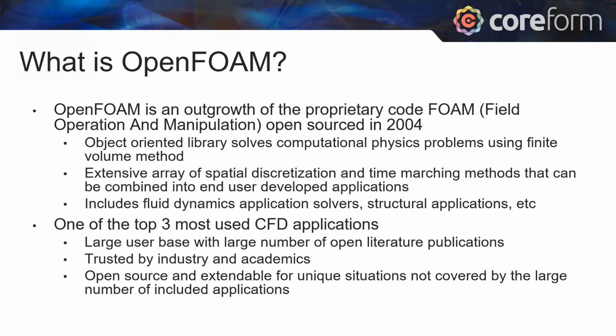It's a sequence of CFD applications and libraries. It's an object-oriented library. It solves, in general, computational physics problems using the finite volume method. They have an extensive array of spatial discretization and time marching methods. The idea was that you would take those methods and combine them into an end user developed application. In the process, they developed some internal applications that they would put out there.